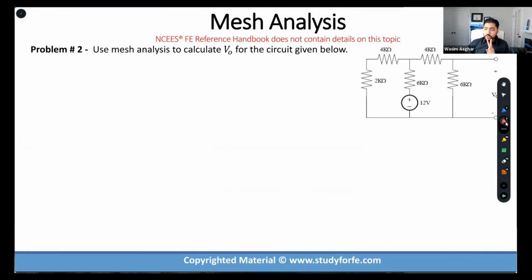So two very simple things I want you to remember. When it comes to KCL and KVL, we've already discussed the voltage gain and voltage drop. That's one. The other thing we discussed was arbitrarily switching the direction of the current when you move from one node to another node. That was the second thing. The third thing, please take it to heart, memorize it: always keep these loops in the same direction when you write the math. That is a rule.